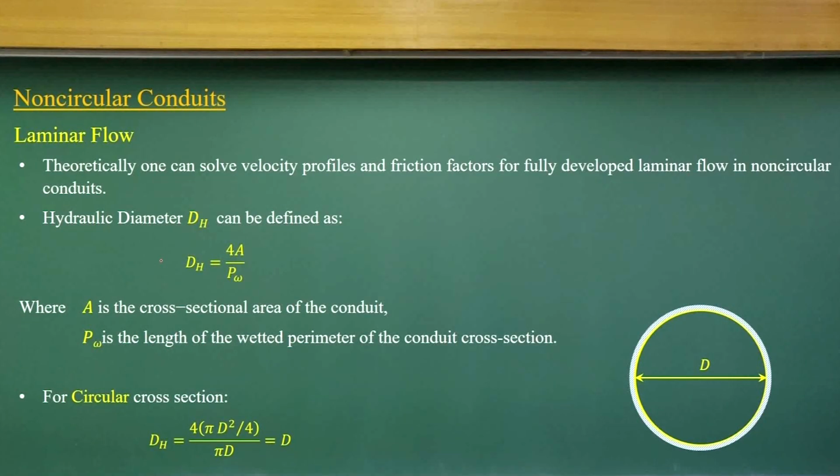So, that means we introduce a hydraulic diameter. It is called the hydraulic diameter, which is a function of area and wetted perimeter. The part of the perimeter which is under wetted conditions is the wetted perimeter. Like, for example, if I have the flow in a pipe going through full, then I can consider the total perimeter as the wetted perimeter.